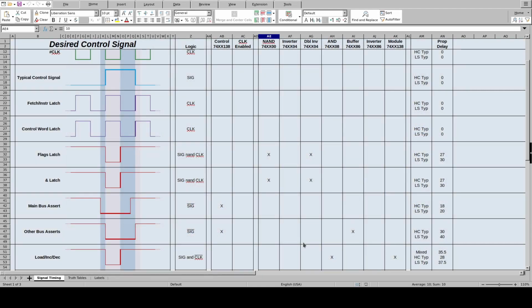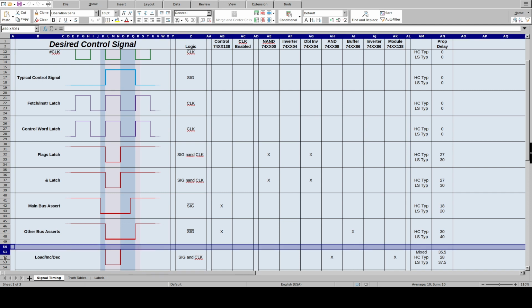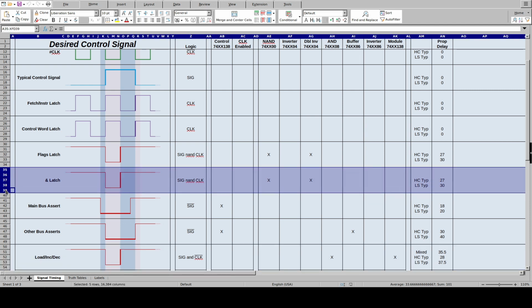At this point, I'm almost wondering if it doesn't make sense to create a 4-cycle clock as opposed to a 2-cycle clock, meaning I have a 4-phase clock cycle where they're both low, one's high, they're both high, one's low. This 84 nanosecond delay in here between this signal and that signal is material.